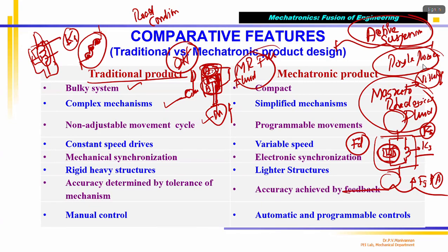Apart from that, above the damper, I have a magnet coil. I supply voltage to this coil, so there is a current flow, and the coil produces magnetic flux. By varying the current flowing through the coil, I can change the magnetic flux. If I vary the magnetic flux, the viscosity of the MR fluid changes, so the damping force FD changes. This is called an active damper, correct?